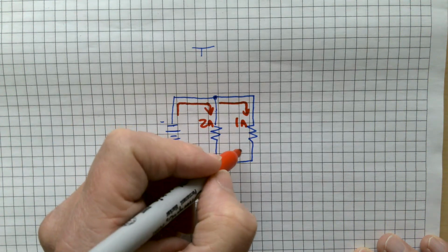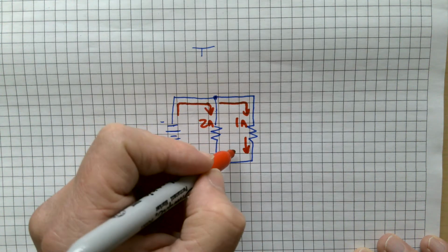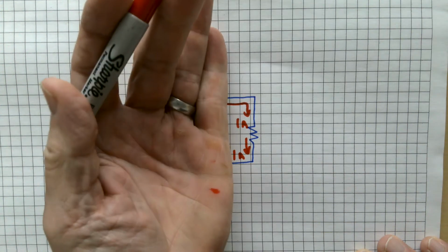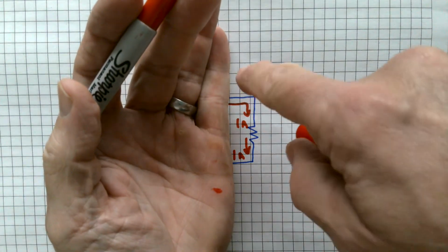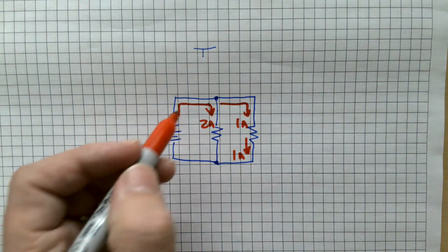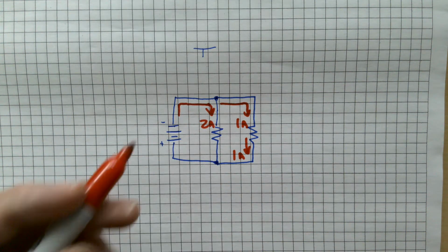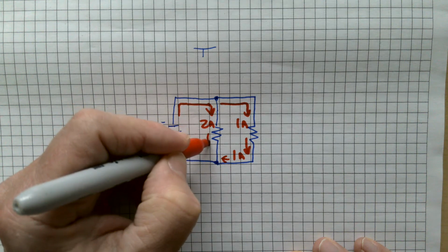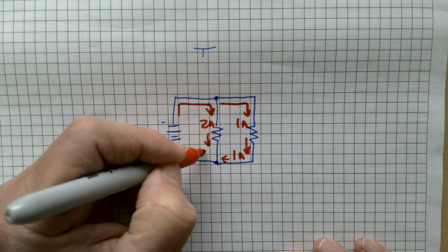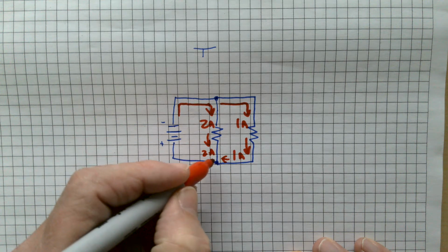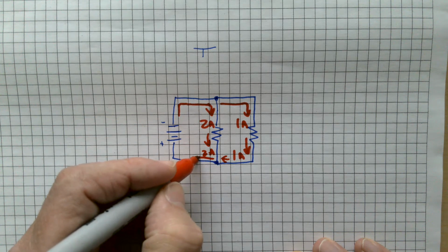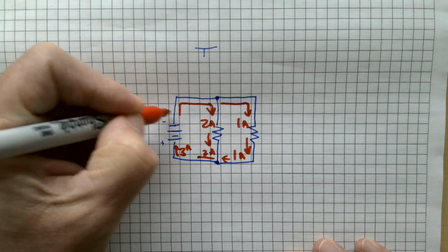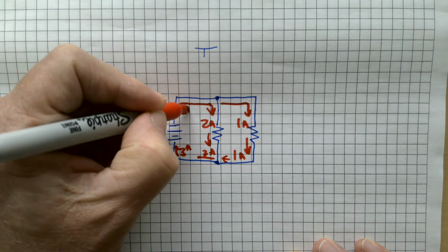Okay, coming out the other side of this resistor, we're going to have 1 amp. It doesn't change because here we have kind of a series circuit. It has just this path. But since we have a parallel circuit, we have multiple paths. So that 1 amp is going right here, and we have 2 amps still being used by this little branch, 2 amps. And right here, they join together, and we have 3 amps going back into the battery, which means that we're using 3 amps.